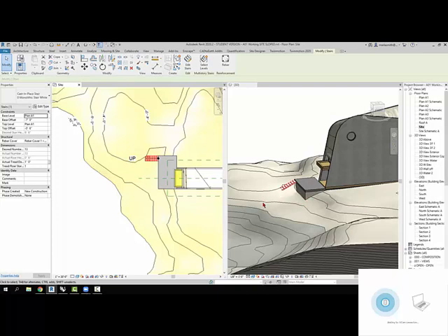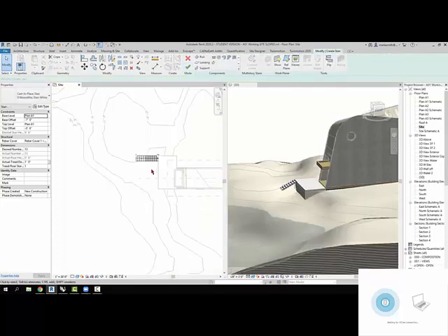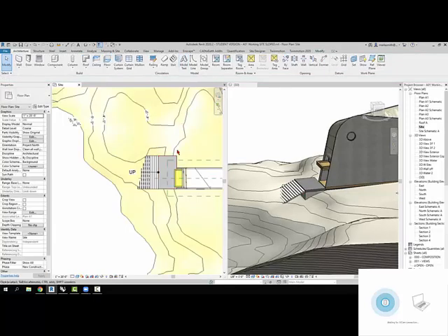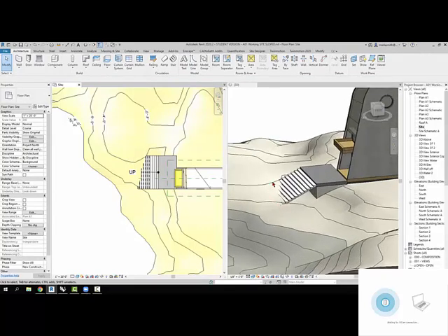And so I'm going to need a building pad sort of down at the bottom, you know, to accept those stairs. The other thing I'll do is I'll edit the stairs here, select them, and I just want those to be as wide as the patio. So we'll make that 18 feet wide for right now, right? So I'll hit check, right? And so you can see the stairs are kind of coming out here at the bottom.